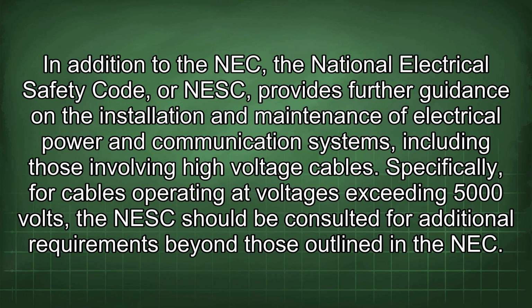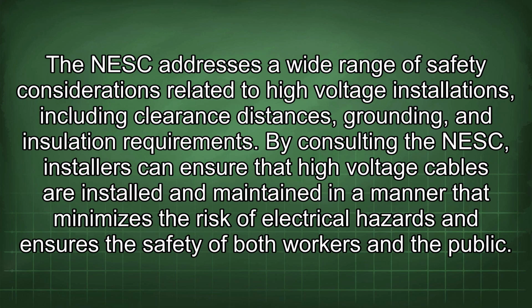Specifically, for cables operating at voltages exceeding 5,000 volts, the NESC should be consulted for additional requirements beyond those outlined in the NEC. The NESC addresses a wide range of safety considerations related to high-voltage installations, including clearance distances, grounding, and insulation requirements. By consulting the NESC, installers can ensure that high-voltage cables are installed and maintained in a manner that minimizes the risk of electrical hazards and ensures the safety of both workers and the public.